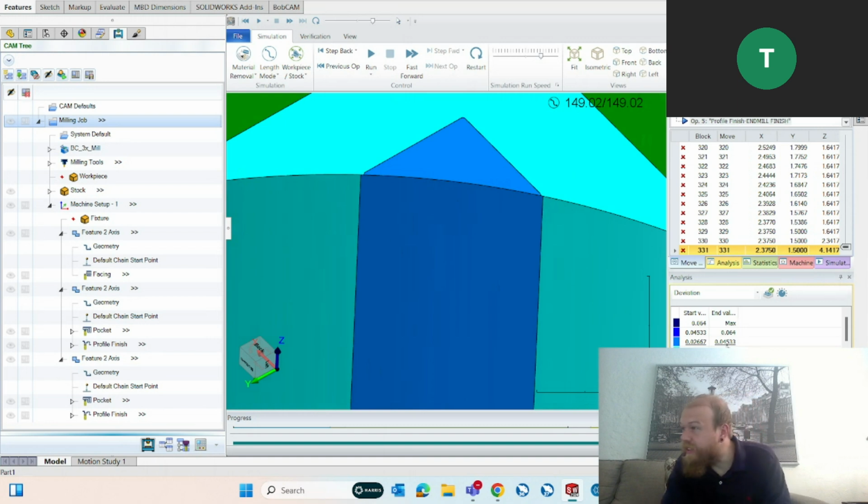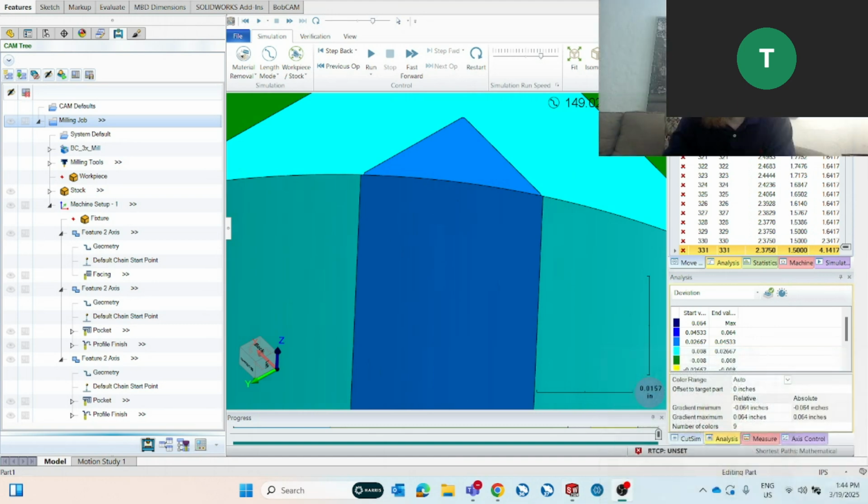I don't know if you can see those colors or the definitions there, so I'm going to move myself to that top right corner now. Now you can see the green here, where my cursor is, plus or minus 8 thou. The teal color here, 8 to 26 thou. Light blue color from 26 to 45. You can see this darker blue color of anywhere between 64 thou or more remaining, which would be much more material to be removed.